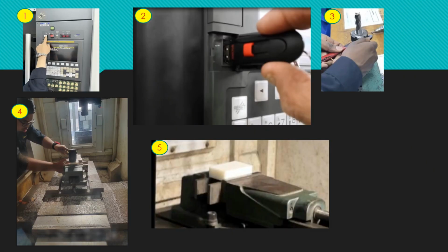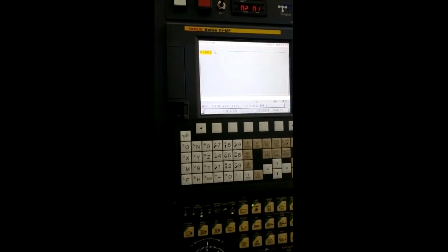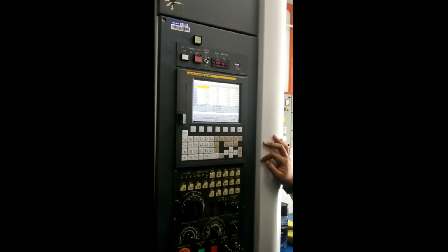Before beginning the machining and manufacturing processes, the machine must be set up first. Then, the program must be sent from a pendrive via USB to the CNC machine. Third, adjust the tool to the one we will be using and set the tool offset for CNC cutting. The workpiece must be put in the fixture in order to establish the coordinate data for X, Y, and Z. Finally, after finishing all the operations, we must start the CNC machining process. Here is a video showing our procedure as the machine is being operated.